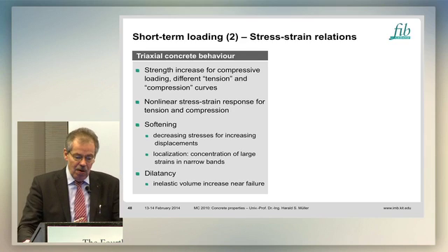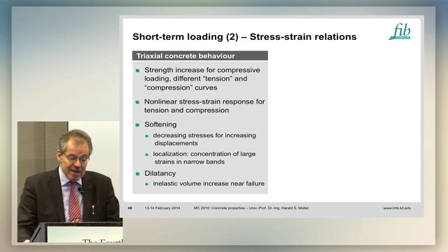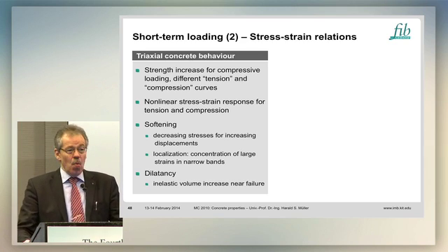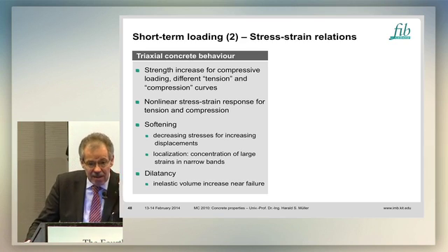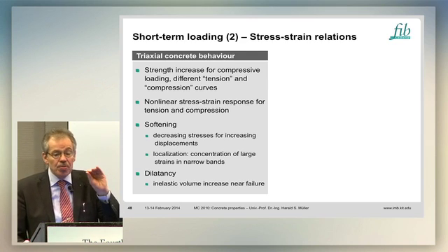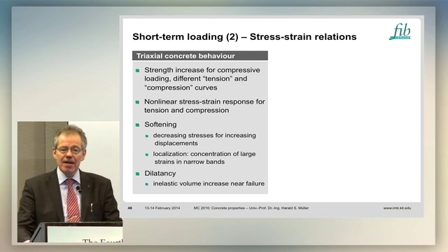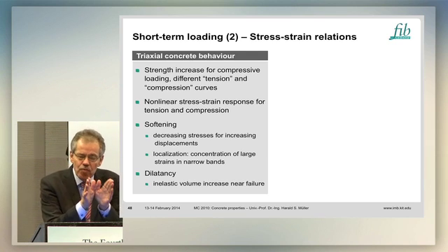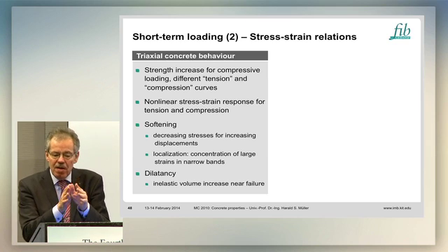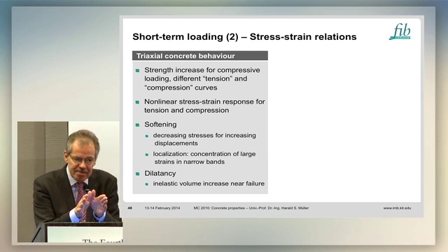Then we also have to deal with the short-term loading, the stress-strain relation, and the triaxial concrete behavior. We did not do this in Model Code 90. In Model Code 90, we had looked also at the biaxial stress-strain behavior of concrete, and if you remember, we modified a little bit the model of Darwin and Pecknold.